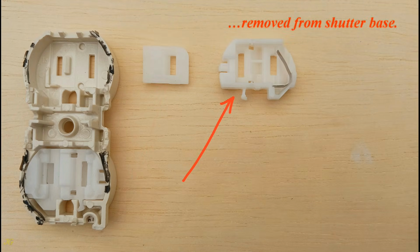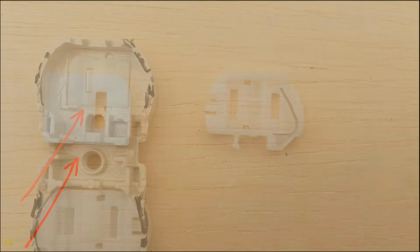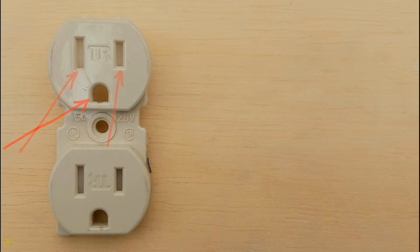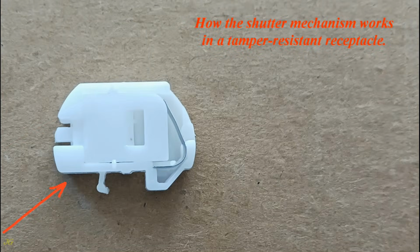removed from the shutter base. The flat surface of the shutter fits into a recess in the base of the front receptacle and covers both receptacle slots, preventing any object from being inserted into these slots. The grounding slot in the receptacle is always open. How the shutter mechanism works in a tamper-resistant receptacle.